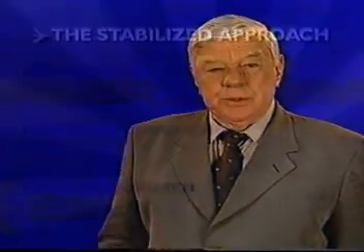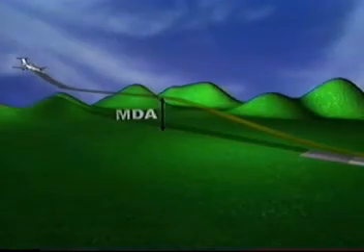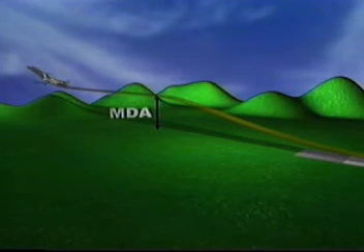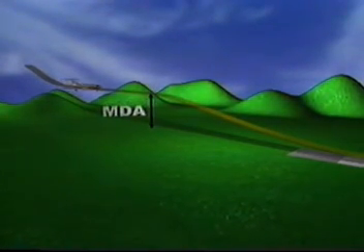Flying the stabilized approach concept is a goal that sometimes cannot be reached due to emergencies or ATC requests. To give you support to fly at that desired concept, let's discuss some interesting approach conditions. Non-precision approaches. It is well known that non-precision approaches may have a minimum descent altitude, MDA, in which the aircraft is leveled off and maintained until one has visual contact with the runway.